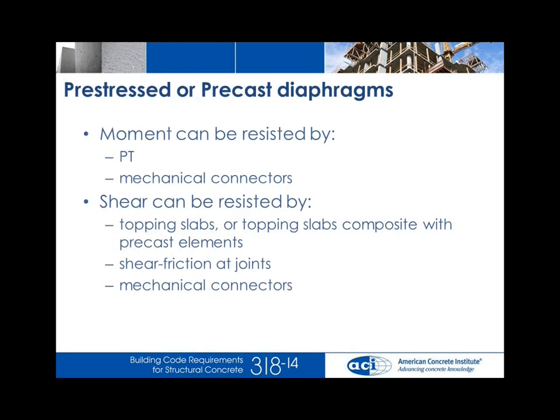Only one slide on pre-stressed and precast diaphragms, so we can finish in a reasonable time. There's a lot of detail if you get into these different systems. We're not going to go into them, but I would like to note that if you have a pre-stressed or precast diaphragm, moment can be resisted directly by the pre-stress that exists in the diaphragm.